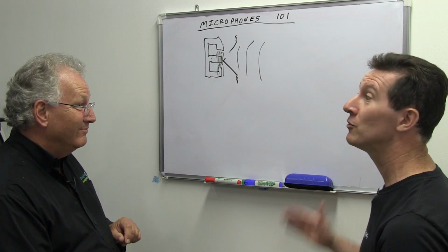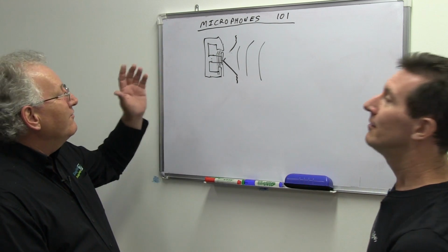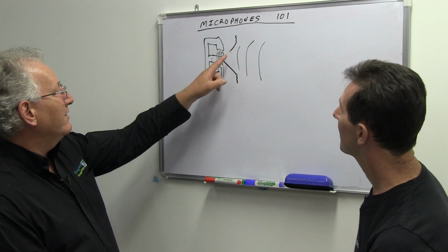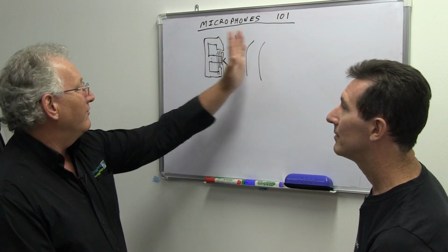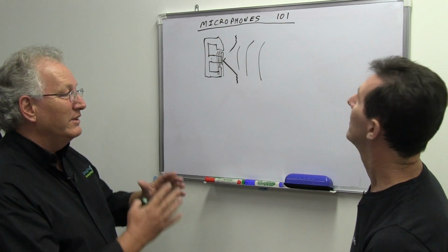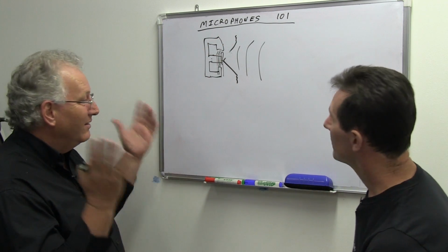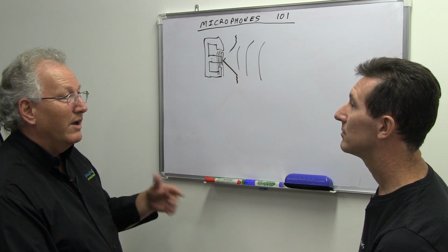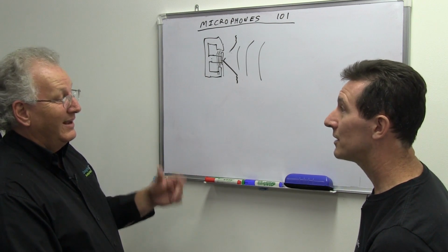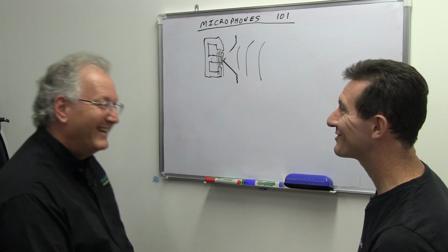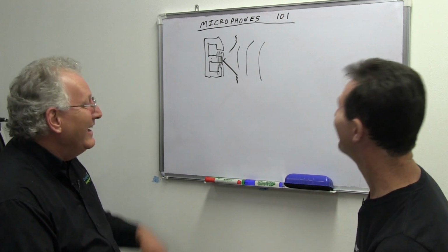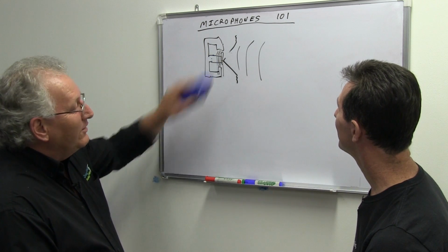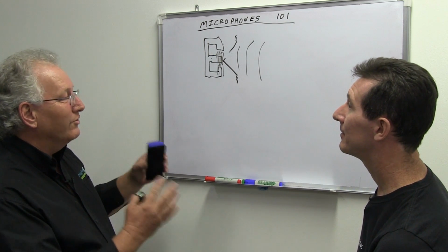You can scream into a huge dynamic range? Yes. There's no fundamental limitation on how loud you take these. The fundamental limitation, in fact, is moving the cone so far that the corrugations around the edge lose linearity. That's probably not going to happen until about 160, 170 or 180 dB SPL. And by then you're deaf. Or a jet engine's just gone by.